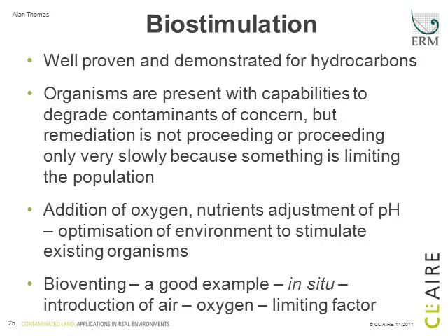Biostimulation is well proven and demonstrated for hydrocarbons. Typically organisms are present with the capabilities to undertake the degradation of the contaminants of concern, and in the bioremediation process we need to add either oxygen, nutrients, etc. to stimulate these organisms and promote and optimize degradation. Bioventing is a good example, where effectively we're looking at oxygen as being the limiting factor, and so through the introduction of air alone we're able to stimulate the in situ microbial population.